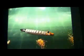In a container ship, where the effective superstructure is more evenly distributed, the drift tracks may be almost straight downwind. We'll try to do the same today in the simulator. In some ships, alterations to heel and trim can be used for fine-tuning of the drift track. Typical alterations for Beaufort 7 conditions are a change of heading of 5 to 10 degrees, resulting from a change of heel angle of 6 to 10 degrees.